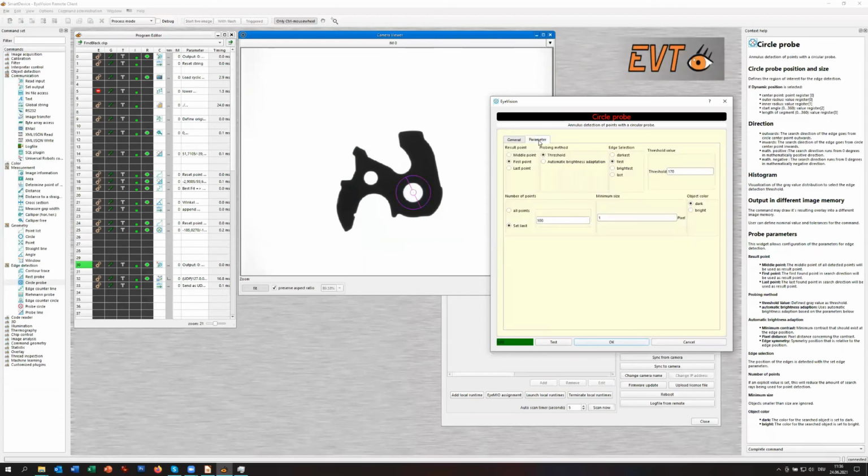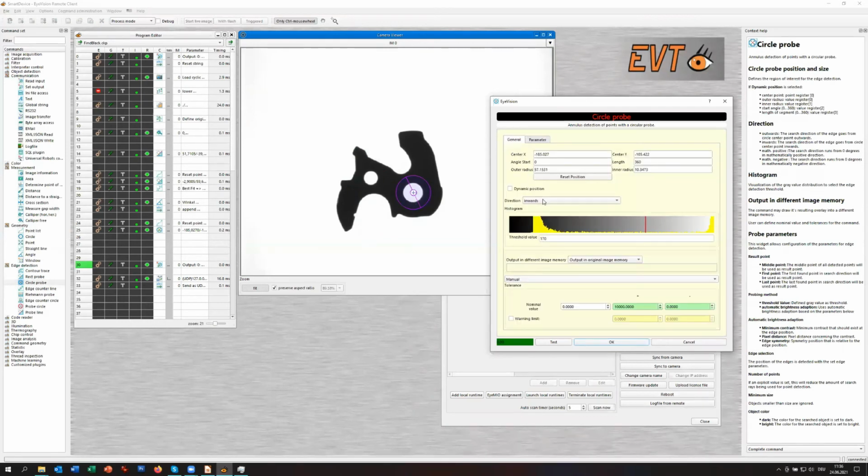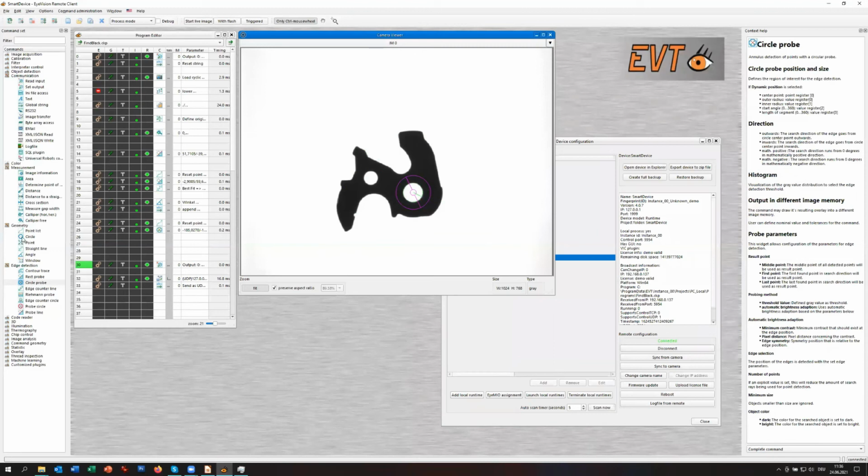And in this case, either we have to select the object color. The object color would be bright, or we say, okay, we start from inward to outward. In that case, the object color is black. That means now we find the dots because we come from a white object and find a black one. It doesn't have to be, as you see, totally black. It works on gray values, even if this image looks like it's not a gray image, it's a real gray image.